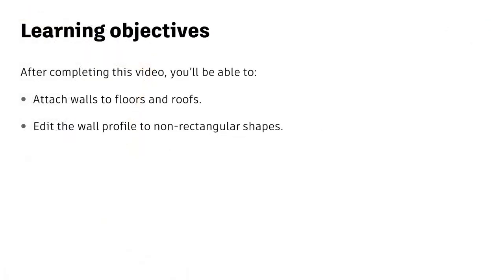In this video, you'll see how to attach walls to floors and roofs, and how to edit the elevation profile of a wall using a sketch to create a custom shape.